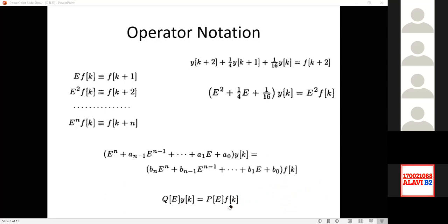You know that the y_ZIR is actually due to the previous initial values of your system, isn't it? And if you do not feed anything new to your system, and your system has some initial values, then what will happen? In general, for a real system, that output will not continue forever. After some time, it will gradually decay out, isn't it?